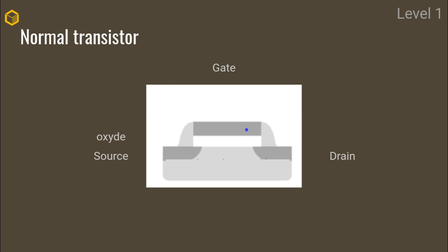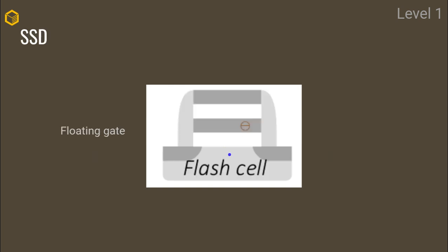And in order to maintain reliability on open and closed states, we isolate with an oxide the gate from the channel. So you can consider this like a barrier where charges aren't supposed to leak. And so your electrons usually don't go from here to here and from here to here.